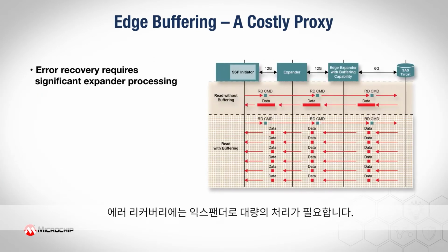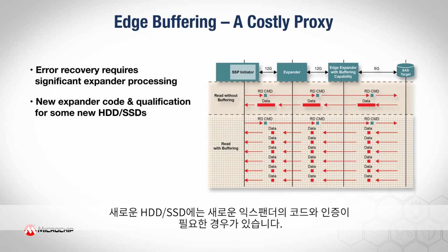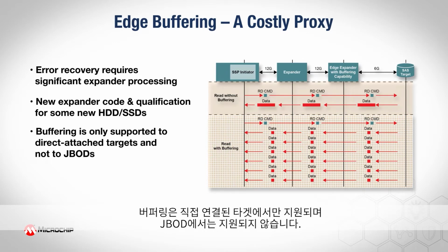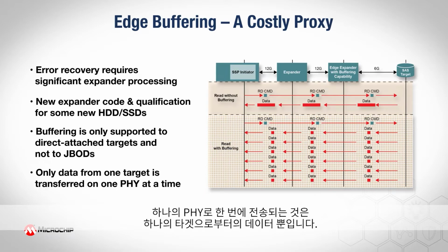Error recovery requires significant expander processing, new expander code and qualification for some new HDD SSDs. Buffering is only supported to direct attached targets and not to JBODs, and only data from one target is transferred on one PHY at a time.